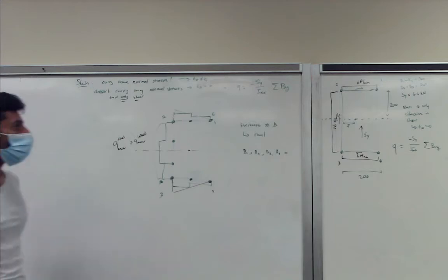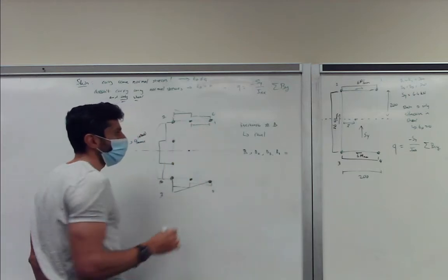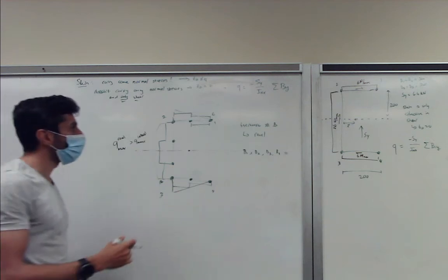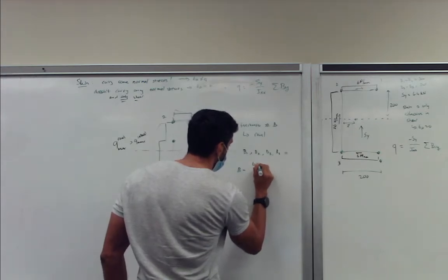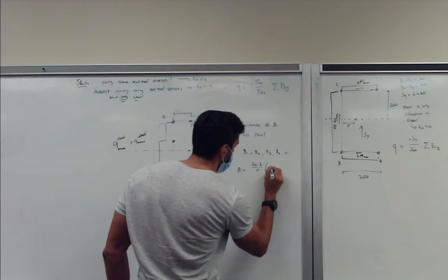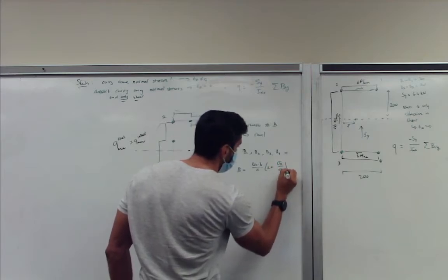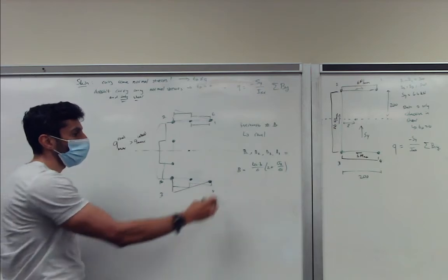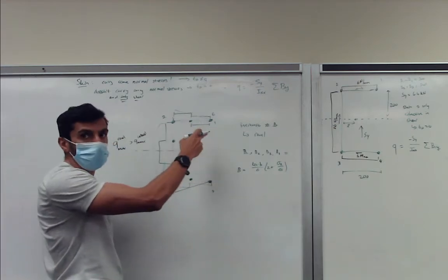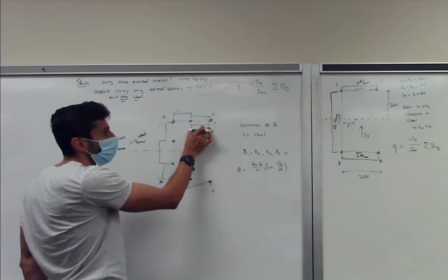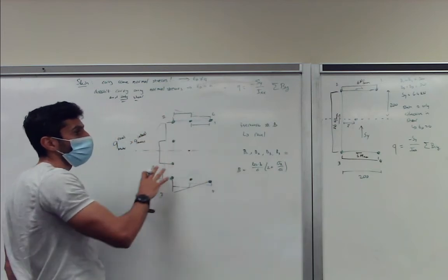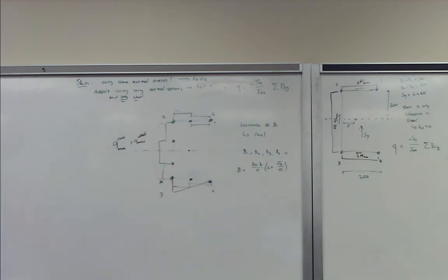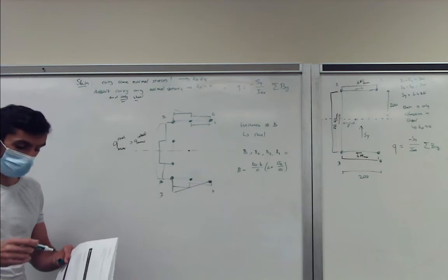Because the boom areas, again, what we did is this contribution, right: B1 was equal to t_D times b over 6, times (2 plus sigma 2 over sigma 1), right? So your skin thickness will probably be the same if you go from real to ideal, but the width of the segment now changes, gets smaller. So you have to update the booms and then re-update the solution procedure. So it's basically an iterative process. If you increase the number of booms, you have to recalculate what the boom areas are.